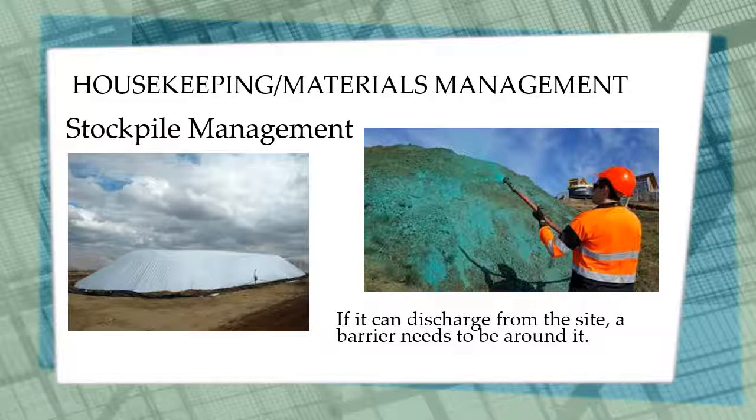There's a lot of possibilities. But again, the critical thing is that it be stabilized if it's going to sit unused for more than 14 days. For dust control purposes, the top of the stockpiles should be flattened.